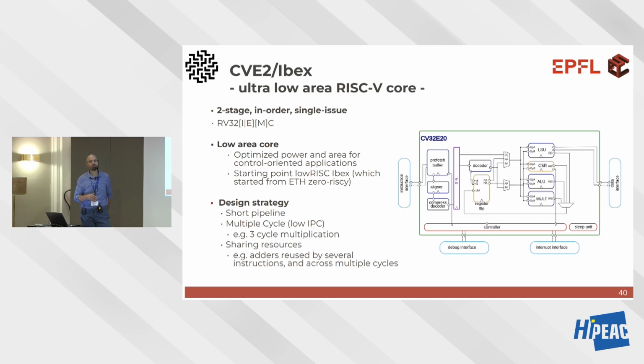So you say that you only need 2 bits to see if what you're looking at is 32-bit or 16-bit? Not only 2 bits, 2 bits and a state to remember. Okay. But if I have jumped to a place, I'm kind of starting fresh. But 2 bits means among all possible instruction encodings, is it 50% of them set aside for compressed, or 25%, or 75%? If you only need 2 bits to decide, then you are really splitting the possible encodings. Yes, correct. Quite nicely.